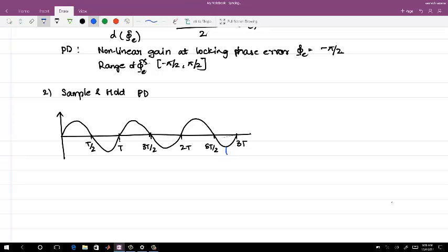This is my V in, and I have a similar V out which is also periodic. Right now assume that they are the same frequency, because we are still talking of phase error detection, not frequency error detection. That V out might be shifted from this sine wave by whatever phase error it has.